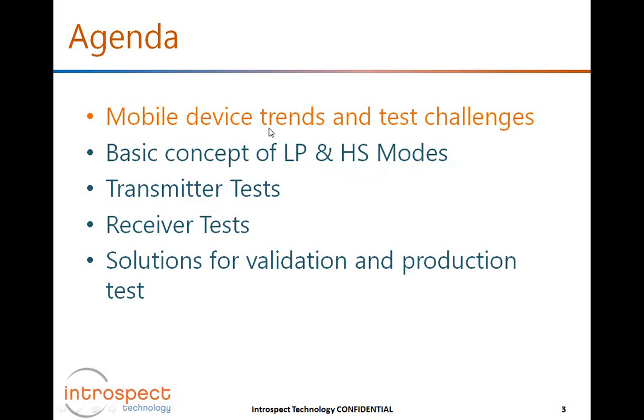And so we'll describe some of these concepts at a high level, and then after that we will use these concepts to define the requirements for testing transmitter devices. In other words, if you're a CPU manufacturer and trying to test how the CPU sends display signals to the display driver, then these are the transmitter tests that you are interested in.